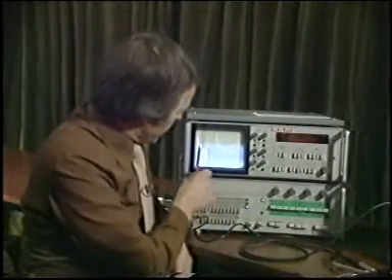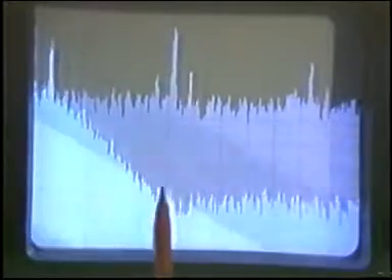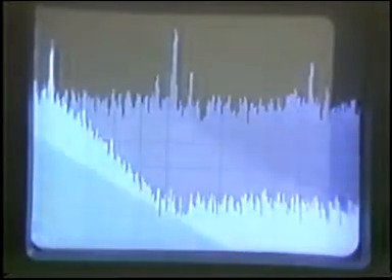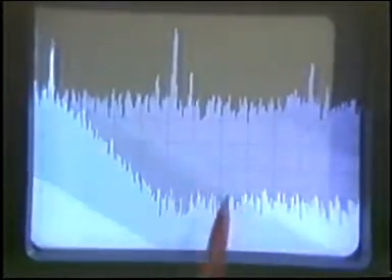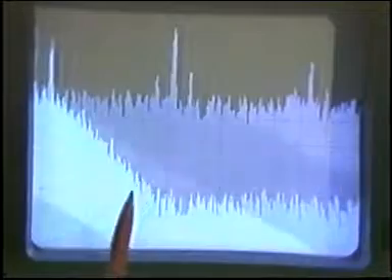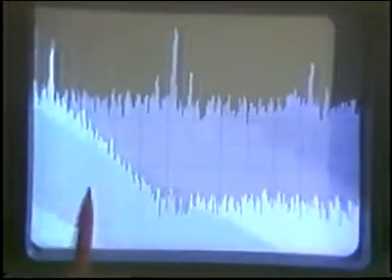We can't filter much nearer to the signal than that without starting to attenuate the signal. And in fact, it wouldn't make very much difference because the noise goes on up to much higher frequencies. So we've taken out quite a lot of bandwidth compared with this little bit just here. So the reduction in noise power is quite significant, and the difference we would make by adding that little bit in as well is neither here nor there.